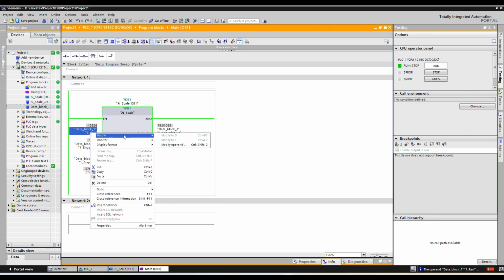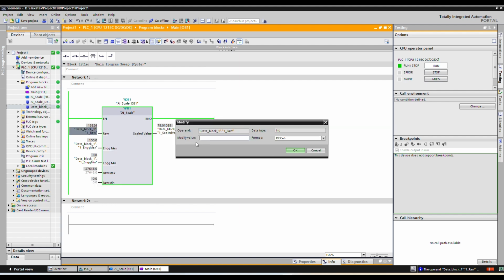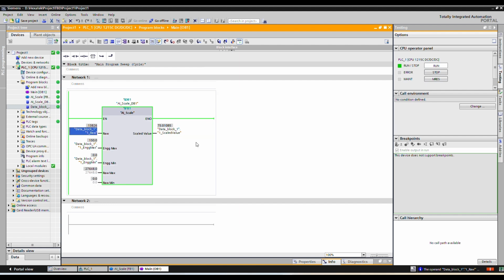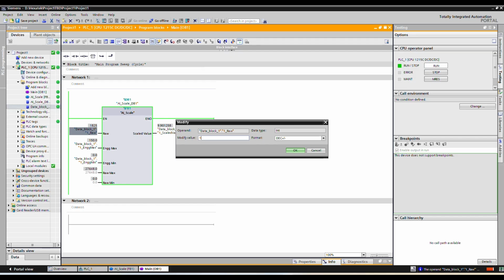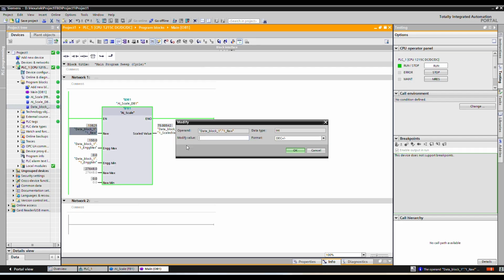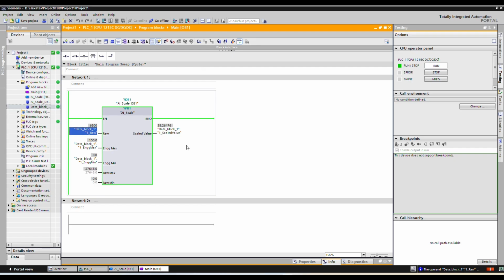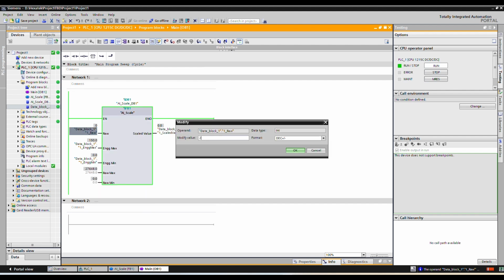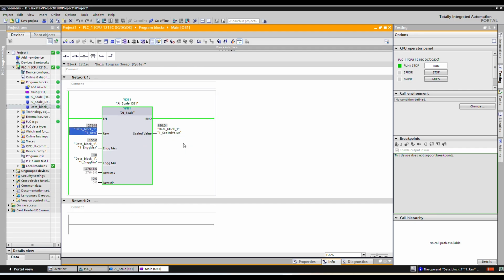so 13824, that is 50% of full range. If we reduce it, 35, and if we make it 0, it will give 0. If we make it 27648, it should give 150.